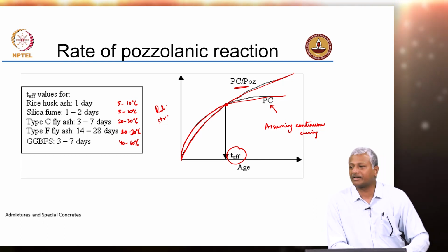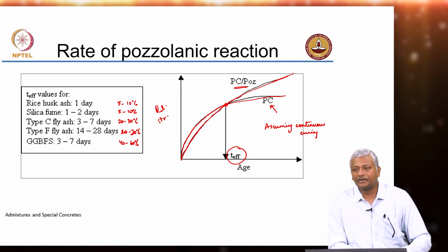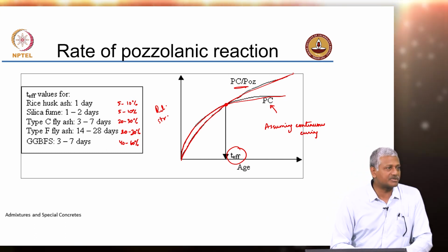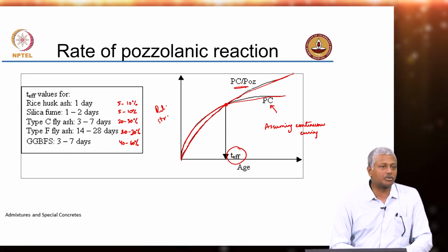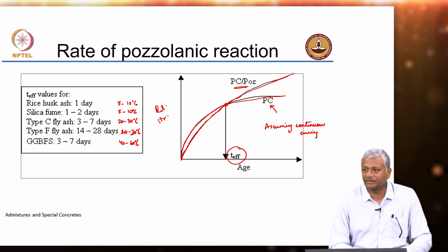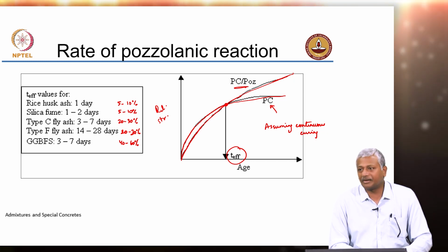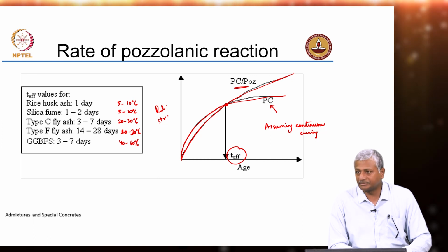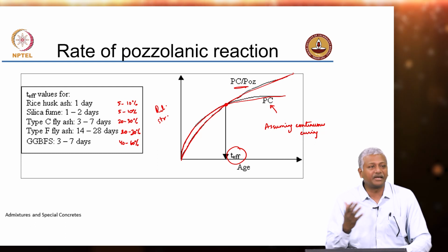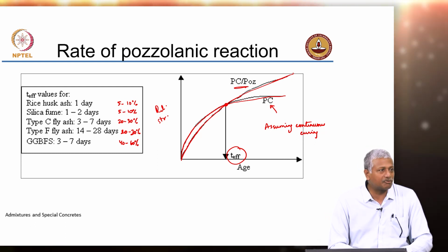Because you have so many factors, even in the limit state design, you assume material factors, you assume load factors. So, very rare that your system will be getting loaded more than 50% or 60% max, very rare. This is in full service. So, during construction, you can imagine that you have much greater leeway in terms of allowing for a greater strength development.